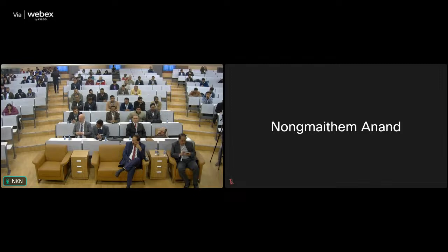For example, the Q value can increase from 0.3, where the rock mass is classified as very poor, to 16.7, which is a good rock. So you see, that's why they have suggested pre-grouting in NMT. They have emphasized pre-grouting very much in their Norwegian method of tunneling.